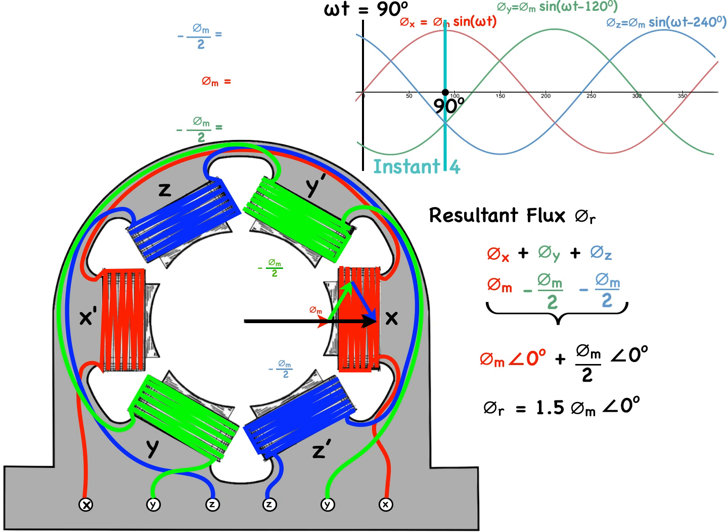So you get the idea of what is happening here. We have picked 4 instants of time, and we found that the resultant flux phasor has rotated from 90 degrees to 0 degrees, and because we did it in steps, it looks like it's 4 steps to the process.